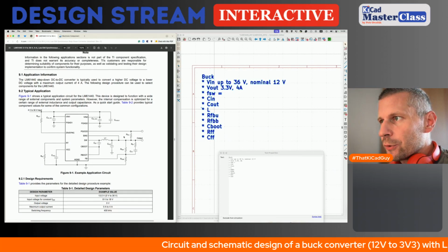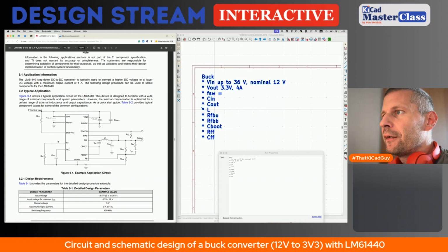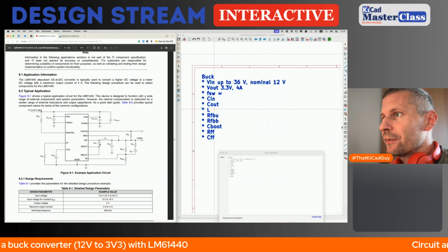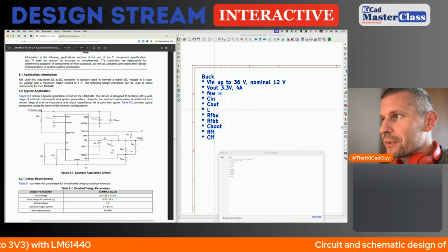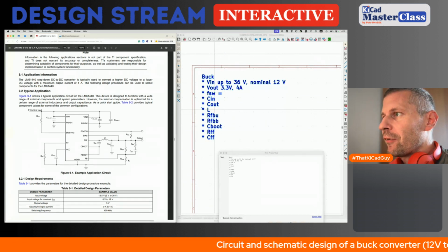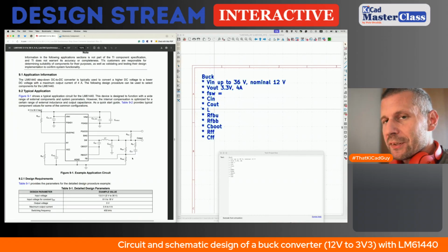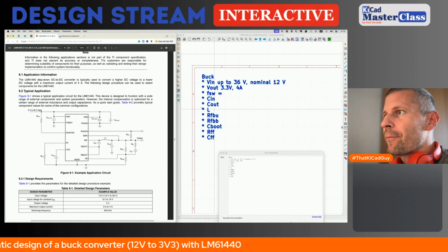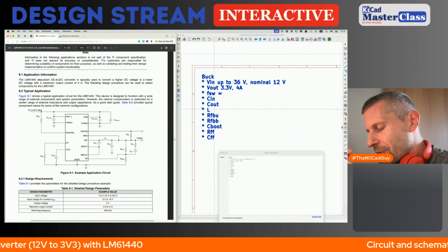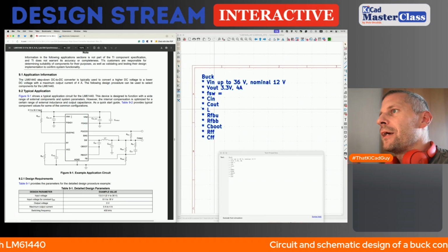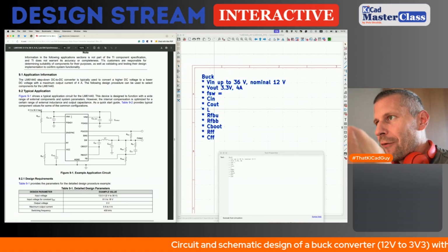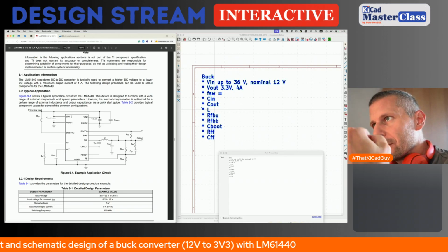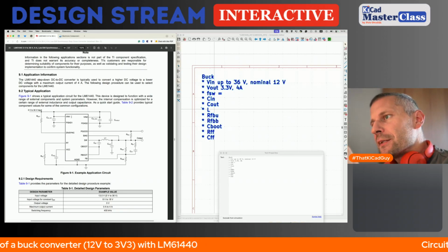So this is how the typical application circuit looks like. It's based on the minimal circuit. There is the bootstrap capacitor, output filter LC, there is the feedback resistor divider with the feedback compensation. There is a power good resistor, not important here. Because the switcher has the topology with dual power entry ports, there are two power entry ports at each side of the IC package.